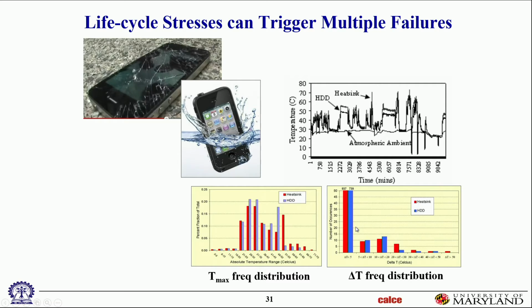So what do I need for that? I need to know how many cycles of what magnitude that history has. So that's cycle counting. Look at this figure on the bottom. I know you cannot read the axes from there. On the horizontal axis is the magnitude of that cycle, and on the vertical axis the number of such cycles. Out here are very large amplitude cycles, and there are few of those. Out here are the tiny cycles, and there are many of those, with some distribution in between. But there are algorithms that will do cycle counting on that complicated profile and convert it into something like this. And this I can input into my fatigue models, and it tells me how many such days I can survive. So extracting information out of data is a big part.